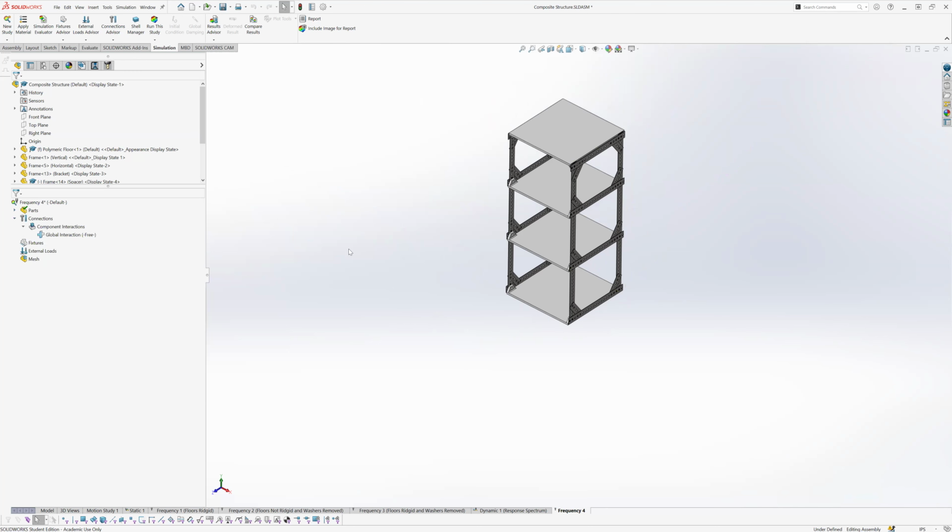Again, there are so many different ways you could set up this analysis. This is just one. So I'm not saying that this is the only right way. I'm not even saying this is a correct way. Obviously, by making stuff rigid, you're getting a little bit more unrealistic, but it never hurts when you're doing preliminary analyses to simplify and make it more complex step by step versus just going really, really complex. And then you may have several issues that you have to try to solve. So that's definitely a way to start off. So the first thing is obviously those are rigid.